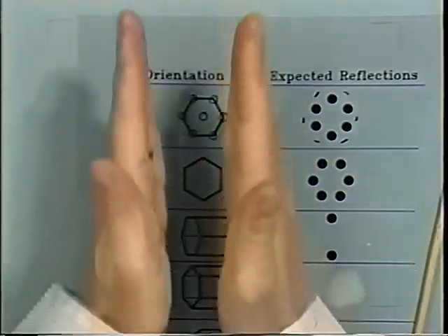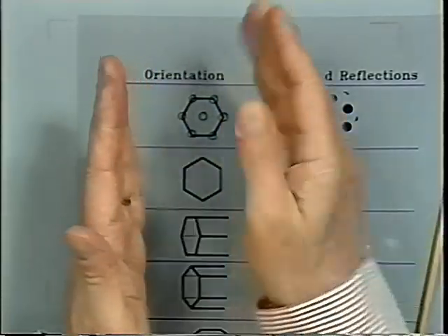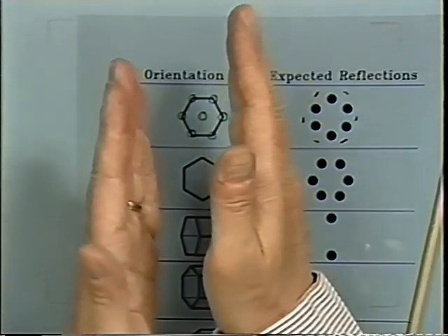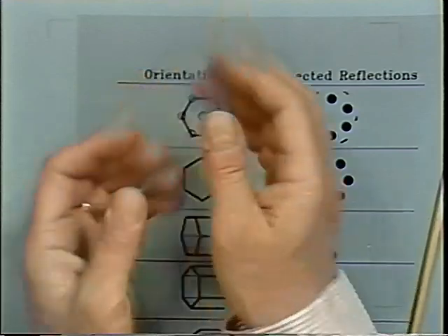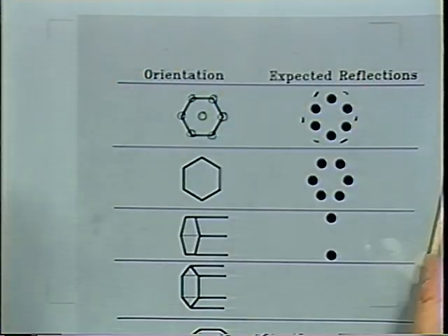flow on those structures. Somehow, when the modulus is high, flow will have a bigger effect on that structure and will break it down more rapidly. But it seems that the hexagon structure, when we talk about the hexagons here, if this is the structure from the side, if you're probing the structure like this, the order hinders the motion of the cylinders drastically, and just small displacement of that structure already gives rise to fairly large stresses.